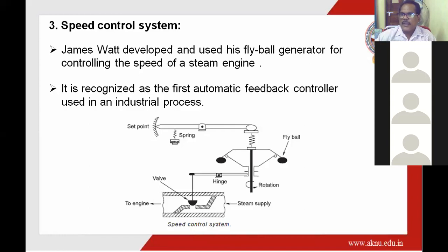Then after the washing, it senses and dries the clothes. After that, there is an acknowledgement signal that the process is completed. All this is nothing but a controlling action. In this controlling action, we have used so many sensors. One sensor senses the weight of the clothes, one senses the level of the water, one senses the time, and one the dry time.